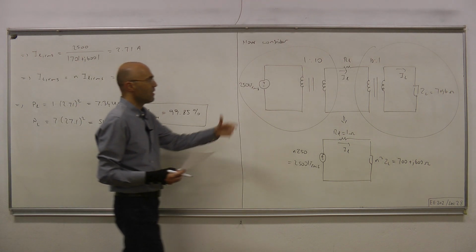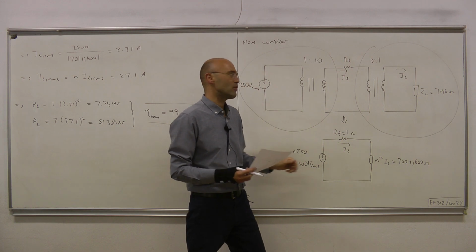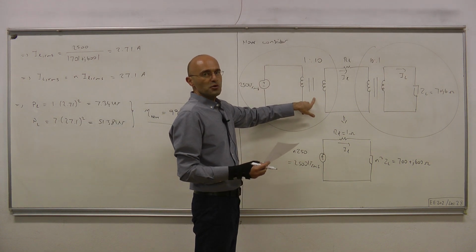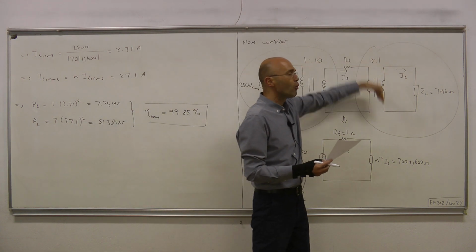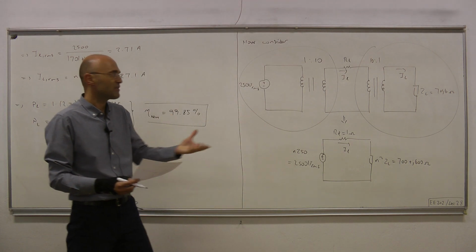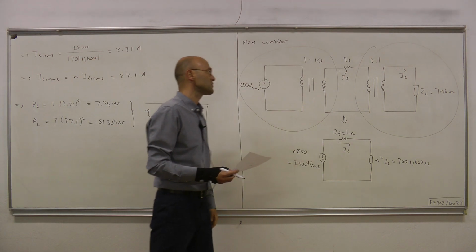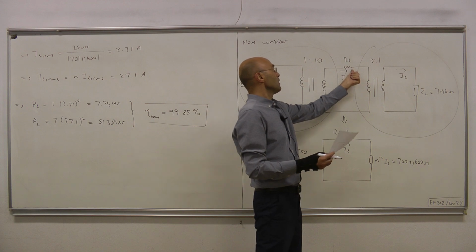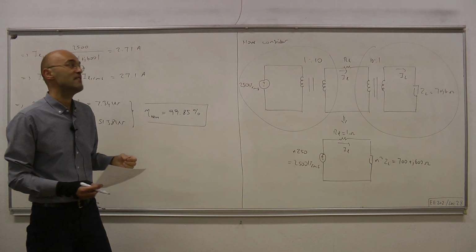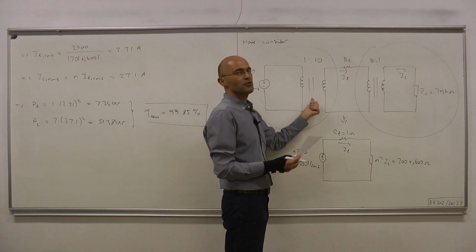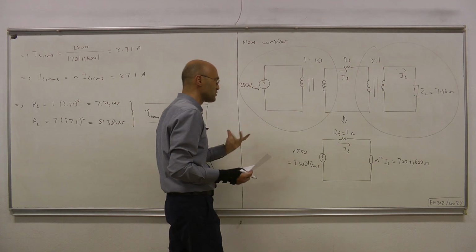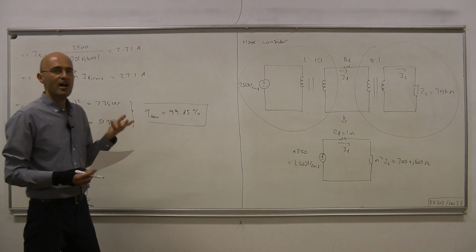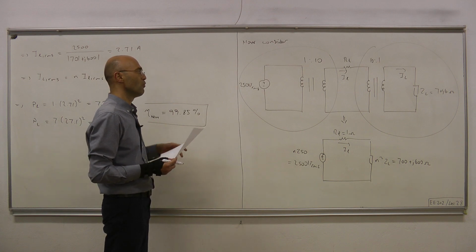Now you may say, in our model we used ideal, in quotes, transformers. And in real life it's true, there will be losses also during this raising of the voltage and then lowering it down. In real life the transformers are not ideal, there will be losses, but those losses are much smaller compared to the losses that we would have had if we hadn't used the transformers in the first place. So that's why almost always the power is transferred at very high voltages over long distances.